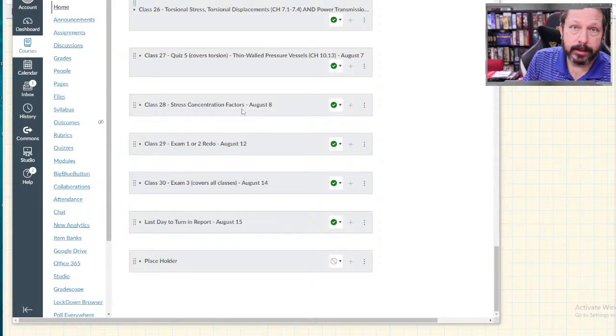We've had distributed loads over a larger area and bearing stresses spread out over an area. But none of this is evenly distributed. The point where you apply that point load has higher stresses than anywhere else. Or if you drill a hole in a plate and then apply a force to it, the stresses are going to be higher around that hole.